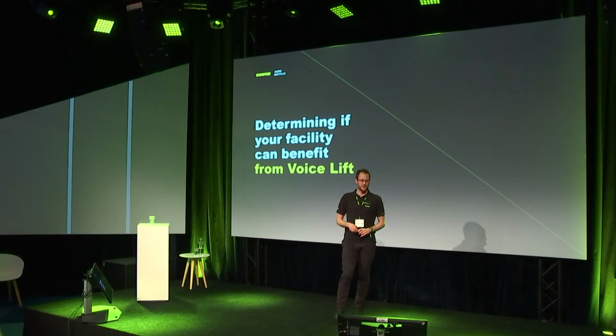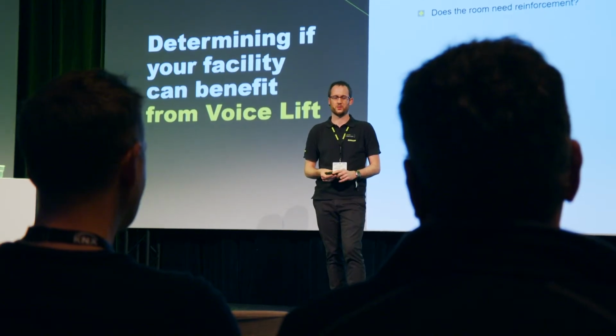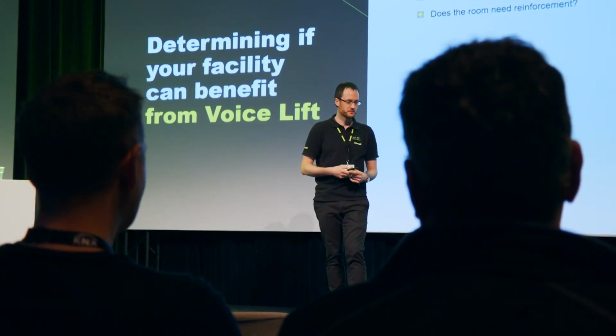Voice lift really works well in some environments, and it really cannot work very well in others. The first rule is the room has to be big enough for the system to be able to cope with the gain before feedback barrier. So are you working in an existing facility with an installed system? Does this room even need reinforcement? Ask yourself the question, are we putting in way more time, money, and effort into this than we can really warrant? Because not all rooms need it.